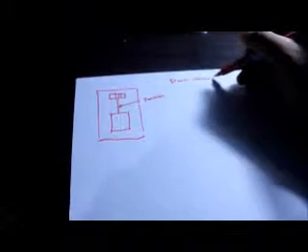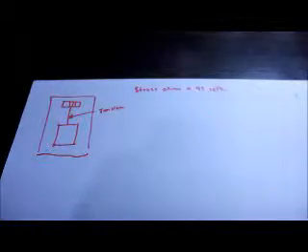For the material we use, which is the nylon string, the allowable stress for that certain material is 45 megapascals. So we all know that stress is equal to force over area. We already know the stress, which is 45 MPa.